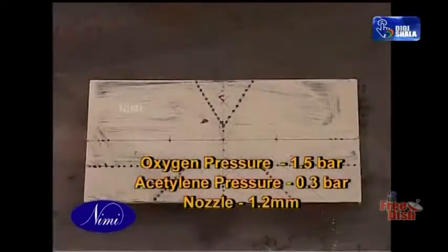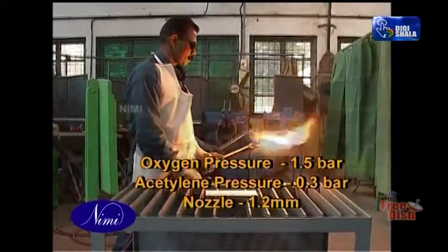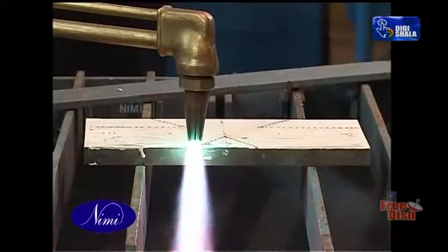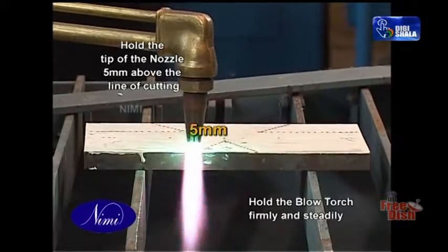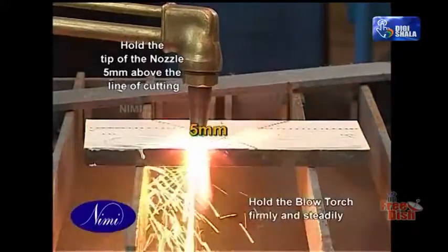For setting the pressure gauges, you can follow the same procedure that we have learnt in earlier lessons. Always maintain a distance of 5 mm between the tip of the nozzle and the workpiece.